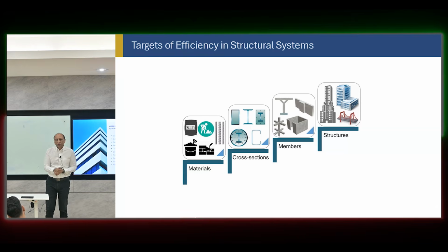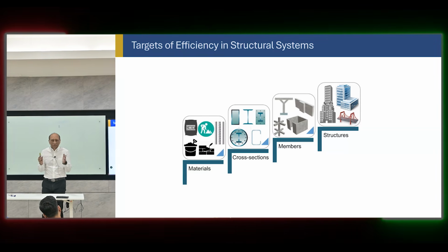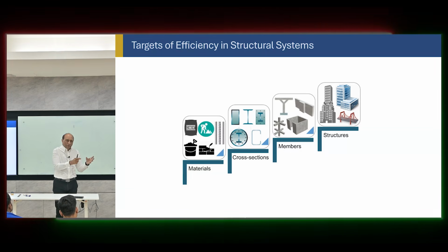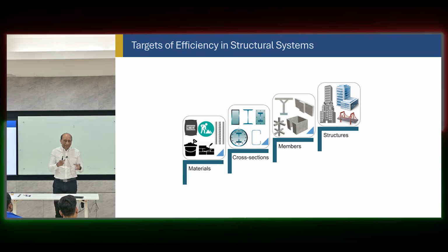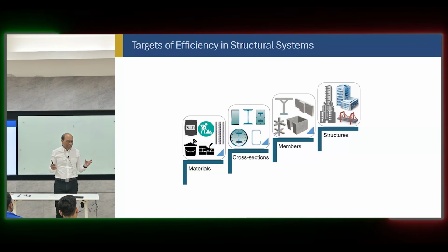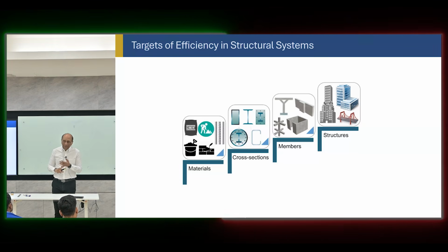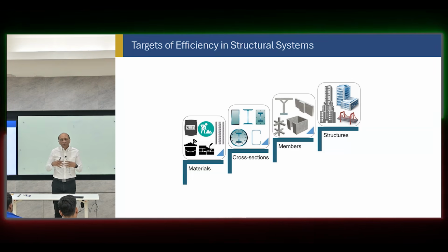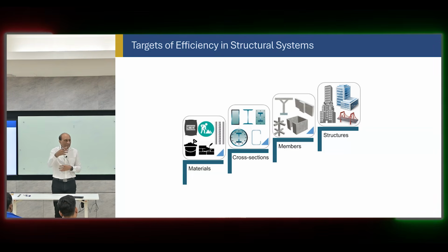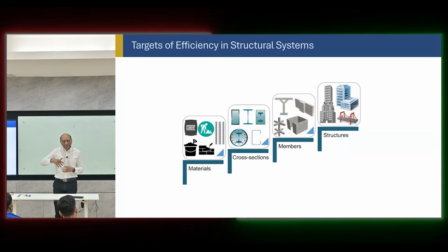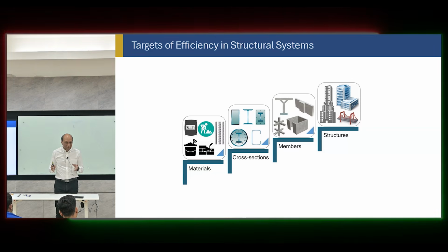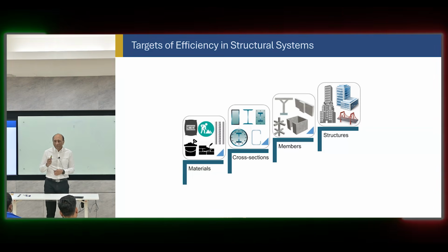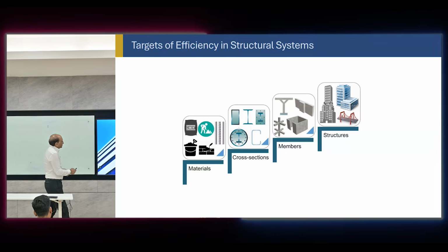Like, for example, if you're choosing a cross-section, the decision between using a high amount of reinforcement and small section, or a low amount of reinforcement and large section, is going to affect the carbon footprint, the space utilization, the construction, the amount of material, cost, and everything. So it's a small decision, but it will affect everything. And we should have a way to measure those effects.